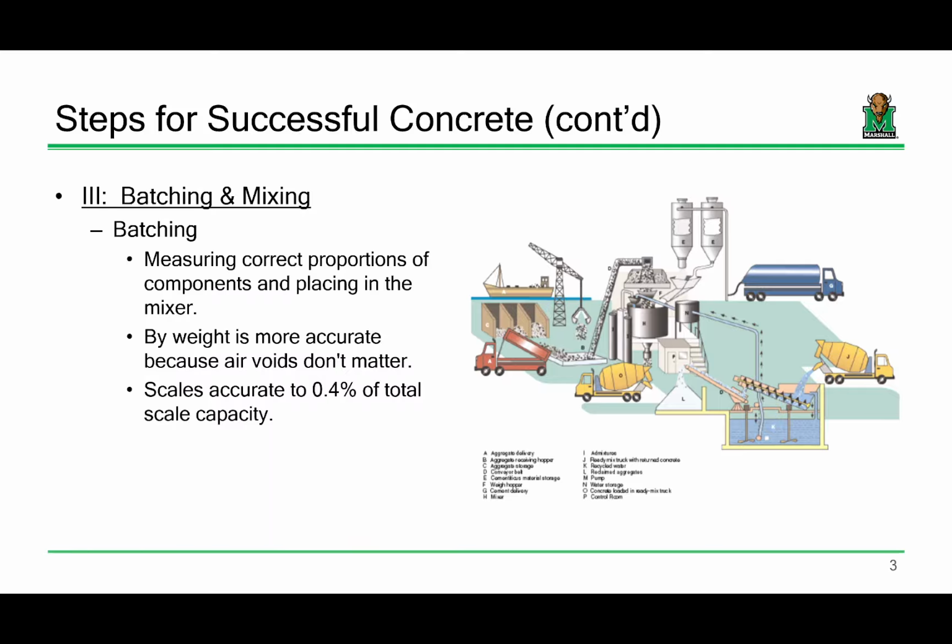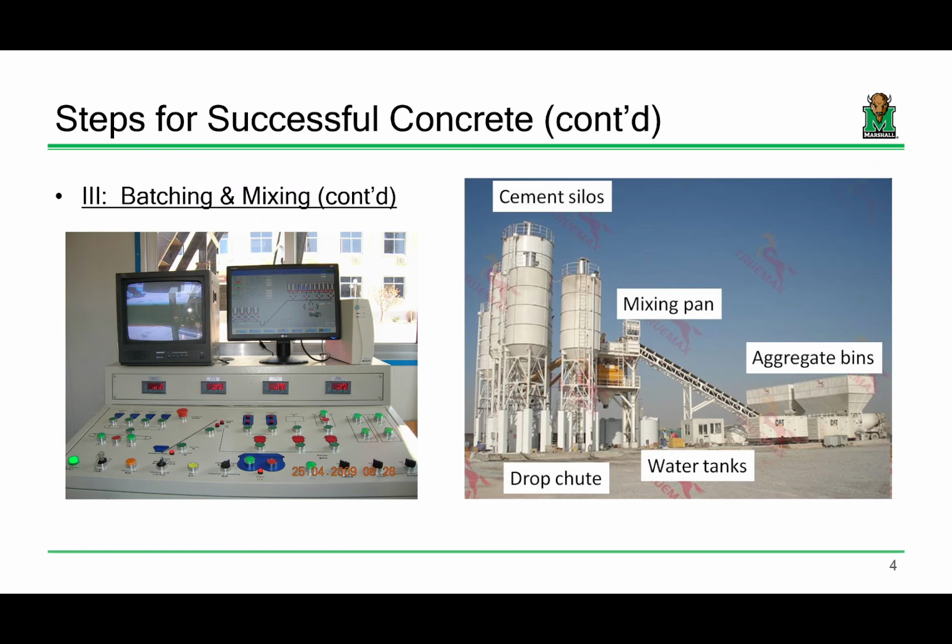One thing to keep in mind is we are batching concrete, which is sort of why, in the mix design process, I was a little fast and loose with rounding. I'm saying let's just round to the nearest pound. It's concrete, okay? Rounding to the nearest pound is fine for your batching. Just to give you an idea, the scales that you're using to measure these components are not accurate to the gram, okay? They're accurate to within a couple points on a percentage, but it's okay if you're accurate within a pound and whatnot.